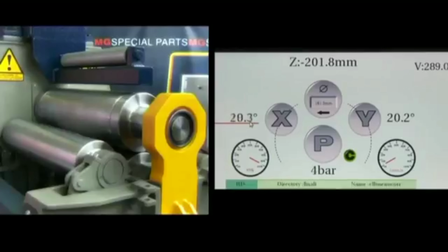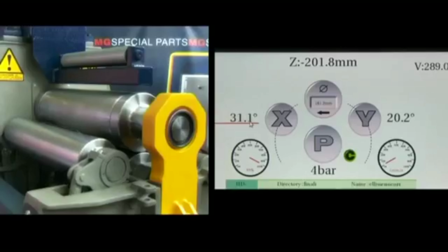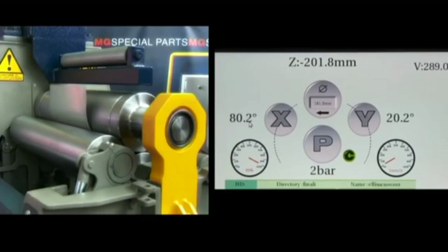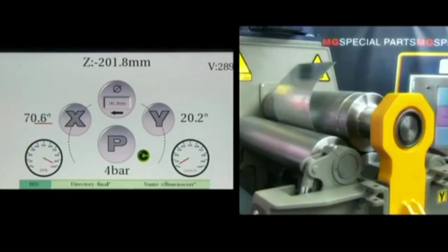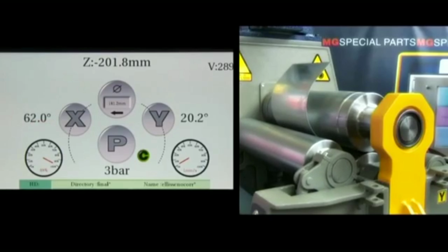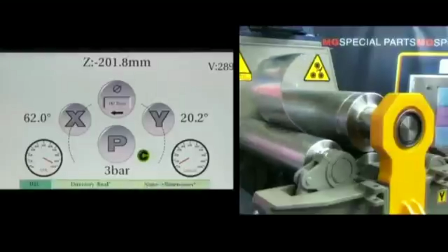As first test angle, we choose a value near the maximum allowed to obtain a small bending radius. As second test angle, we use a smaller value to obtain a rather big bending radius, bigger than the maximum bending radius of the shape we're going to make.